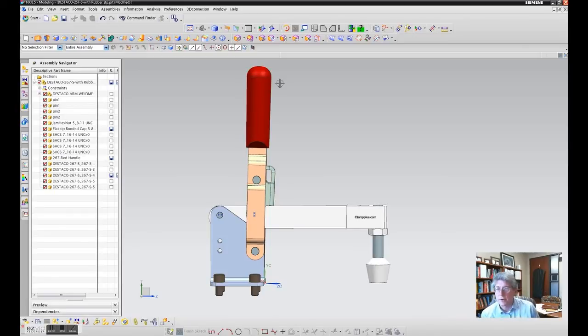But in this particular case, imagine we can flip it a little bit, and I'll say, let's find the force on here. But that also could be posed as a design requirement: can this design survive X amount of force acting on this handle? Now, when you do that, there will be an up force acting here, as well as the forces through the bolts. Okay?